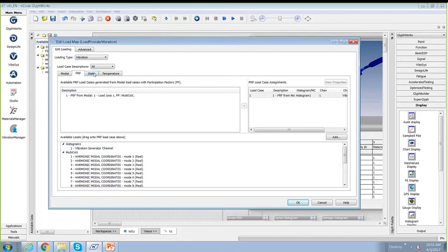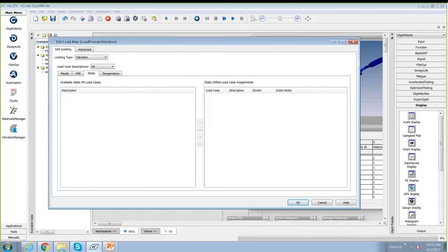Actually, while I'm here, you could also bring in static load cases to make mean stress shifts on the model. You could also bring in temperatures, and I won't run the analysis, but I'll show you a PowerPoint right after this, where I've done a thermal analysis. And so I have an isothermal strain life with the fatigue solver in it.